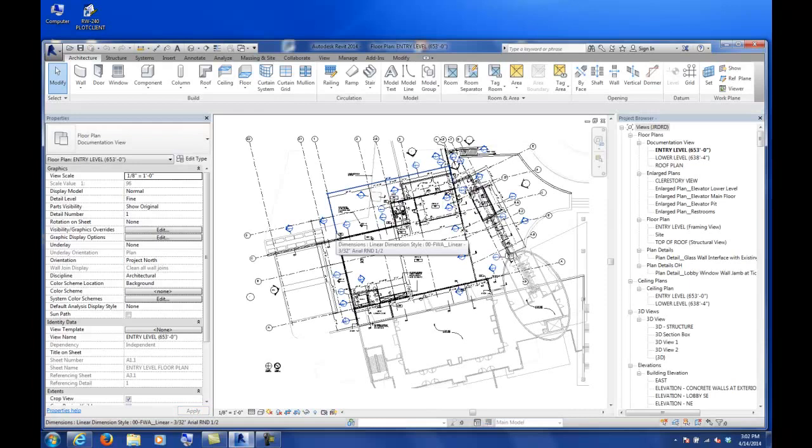The reason you can't move your file from that central location is Revit automatically puts a bunch of links together to make the synchronization happen between the local and your central model. And even if you move it in Windows, say if I copy it onto a USB stick and take it home, Revit will know that you moved it, and you could run into corruption issues. So once it's on that hard drive, wherever that's going to be located, in the server or in the studio, that's where you're going to want to keep it through the next week. Any questions?